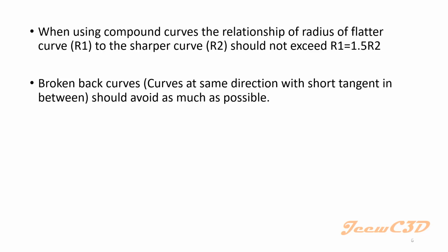So we have to avoid broken back curves as much as possible, because when there's a straight section after the curve, the driver feels that there's a straight portion. So in that straight portion he might increase the speed, but all of a sudden he will come across another curve. So that might be undesirable for the driver, or he might face unexpected conditions due to this curve behavior.